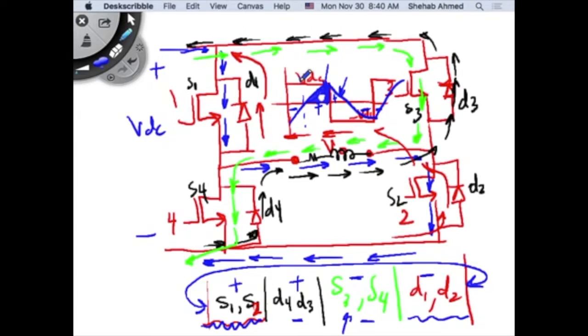So you're going to limit the switching frequency that you can have. If you limit your switching frequency, then you have to live with larger inductors and larger capacitors, if you want to maintain the ripple within a certain value. Basically you will limit switching frequency and you will have to live with larger reactive components.